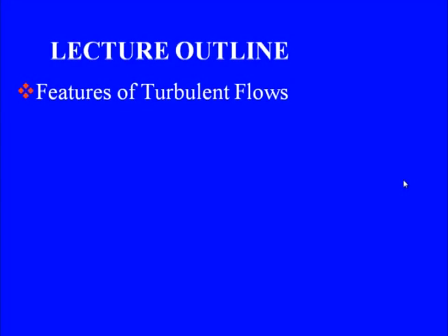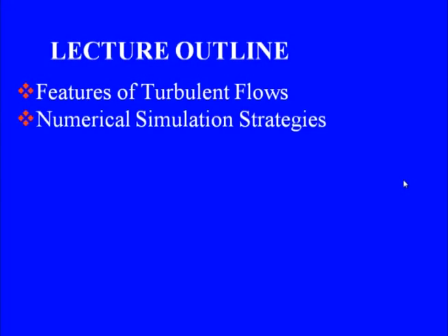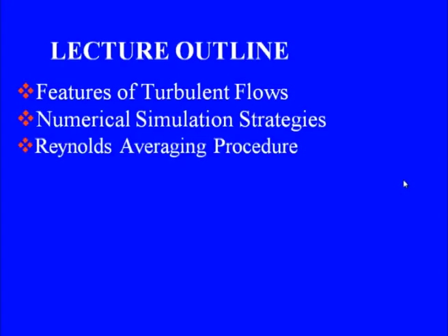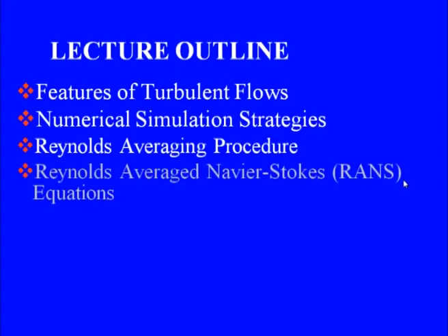So, now let us come to the first lecture in this module, wherein we will have a look at the basic features of the turbulent flows, why we need to worry about the turbulent flows, and what are the simulation strategies which are the ones which are employed in industrial CFD simulations. So, outline of the lecture, we will have a look at the features of the turbulent flows, numerical simulation strategies, and then what is referred to as Reynolds averaging procedure, and if time permits in today's lecture, we will also have a look at Reynolds averaged Navier-Stokes equations which are used in our RANS simulations.